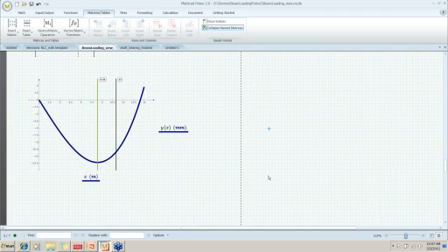How effectively can existing Mathcad 14 worksheets be pulled forward into Prime 2.0? Okay, that's a good one. There's a built-in converter in Prime 2.0 that will convert your existing files into the Prime 2.0 data format. The Prime data format is different from Mathcad 15, 14, and before. It's a totally different format, so you have to run your worksheets through the converter, and the converter is built in.